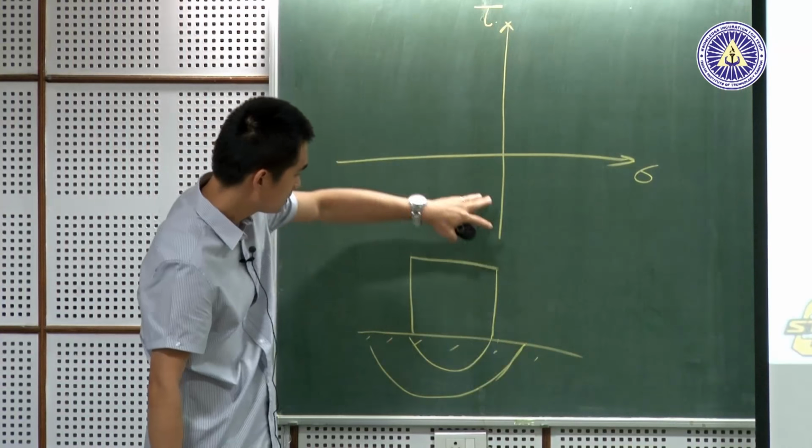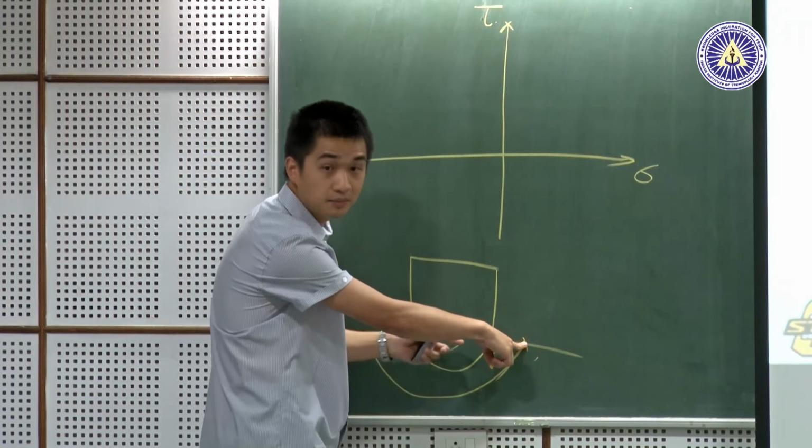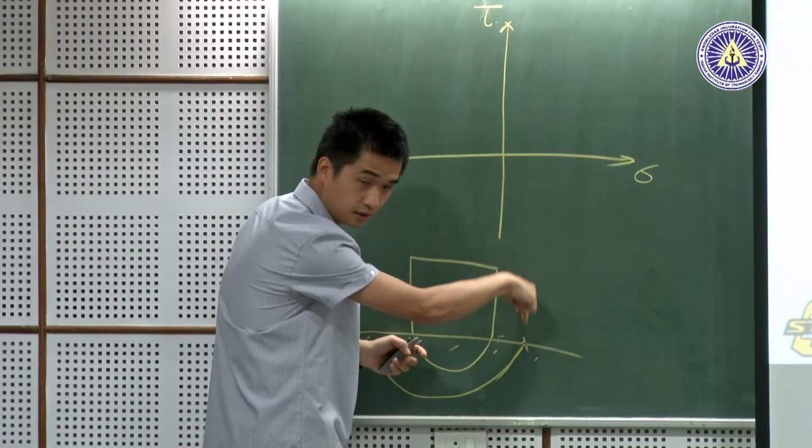Why? We can analyze this with the stress Mohr circle here, because at this point it's a boundary, right? So in this orientation, the normal stress sigma is 0, and the shear stress is also 0, right? So this orientation is located at this point, okay? Then when it has deformation, we know the plastic strength, which we say is k, means at the value of k, it starts to have this plastic deformation.